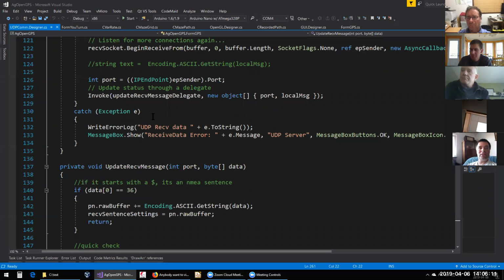I tried it with the new U-Blox F9, and this problem came up, or was even worse, when I used a 10 Hertz GPS rate, and it got better when I reduced to 5. In U-Center I set 10 Hertz satellite rate and output rate divided by 2. So the U-Blox chip only sent 5 times a second, and halved the values of two measurements.